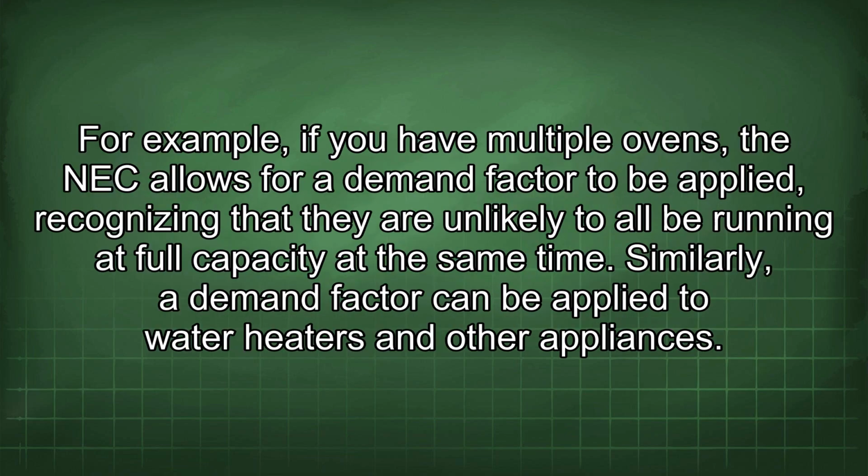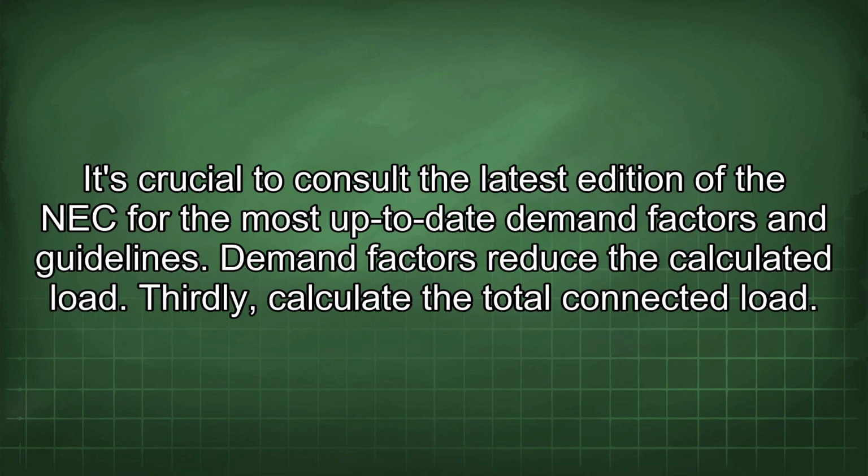For example, if you have multiple ovens, the NEC allows for a demand factor to be applied, recognizing that they are unlikely to all be running at full capacity at the same time. Similarly, a demand factor can be applied to water heaters and other appliances. It's crucial to consult the latest edition of the NEC for the most up-to-date demand factors and guidelines. Demand factors reduce the calculated load.